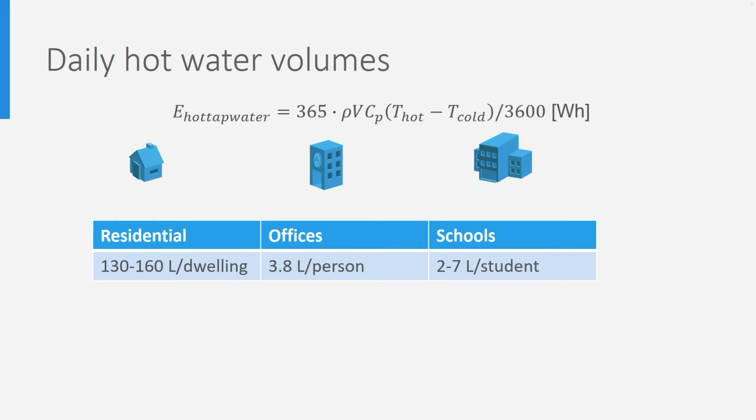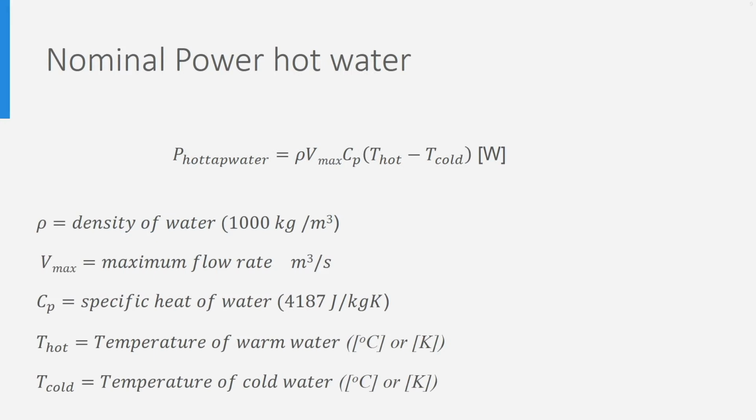For hot water, 45 to 50 degrees Celsius should be enough to deliver the required hot water demand. However, keep in mind that water temperatures below 60 to 65 degrees Celsius have the risk of Legionella bacteria, which cause a health risk.